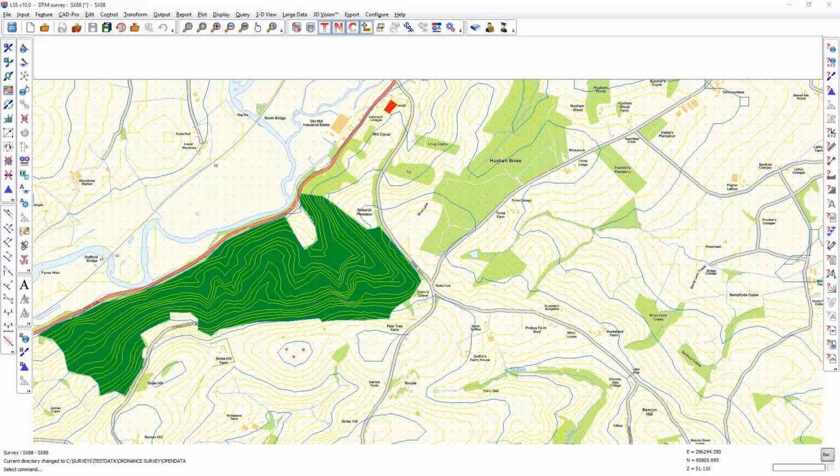The commands output line of sight and query line of sight are fundamentally different to all of the other ZVI and ZTV commands in that, unlike those which look from receptor locations towards the proposed development, the line of sight commands look from the proposed development outwards. And the best way to demonstrate the concept of line of sight is to use the dynamic query line of sight command.